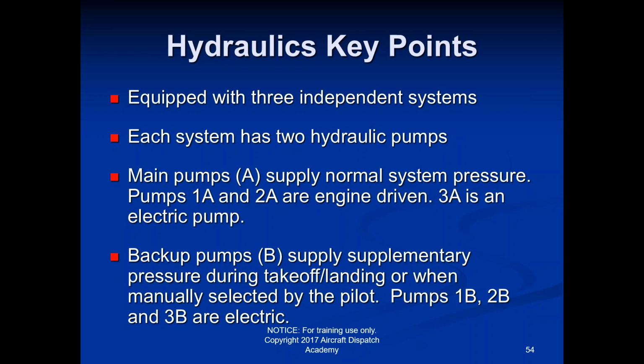The engine can be out, but let's say engine 1 is tied to the aileron and the spoilers and stuff like that on the left wing. Without that 1A pump working, the aileron on that side wouldn't work. But then you can turn on pump 1B, which is electric, and it would still send hydraulics to the aileron. So even though that engine is not working, you could still have control over the aileron and the spoilers, or the landing gear. There are a lot of things that are connected.